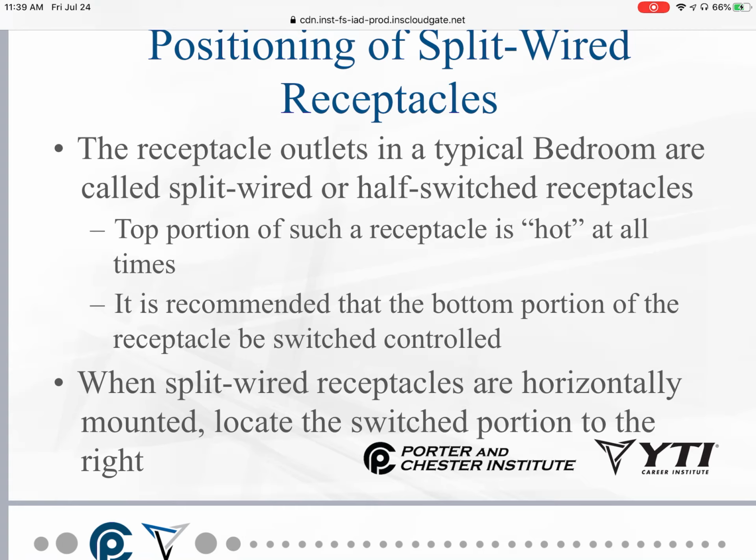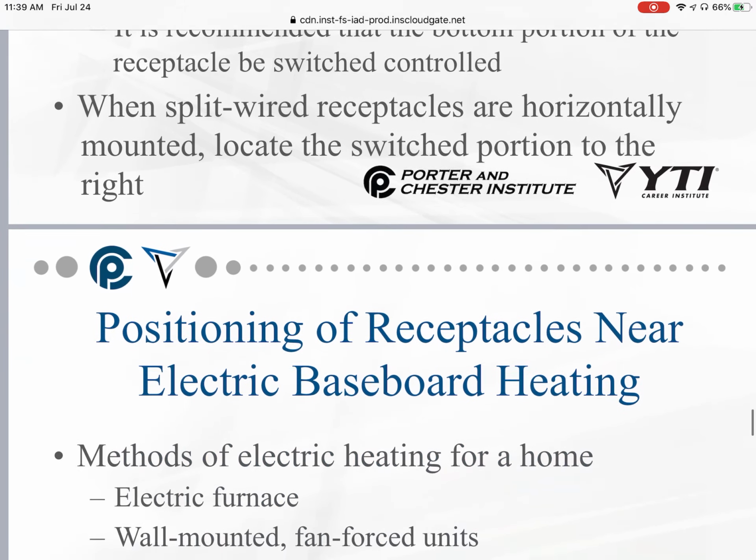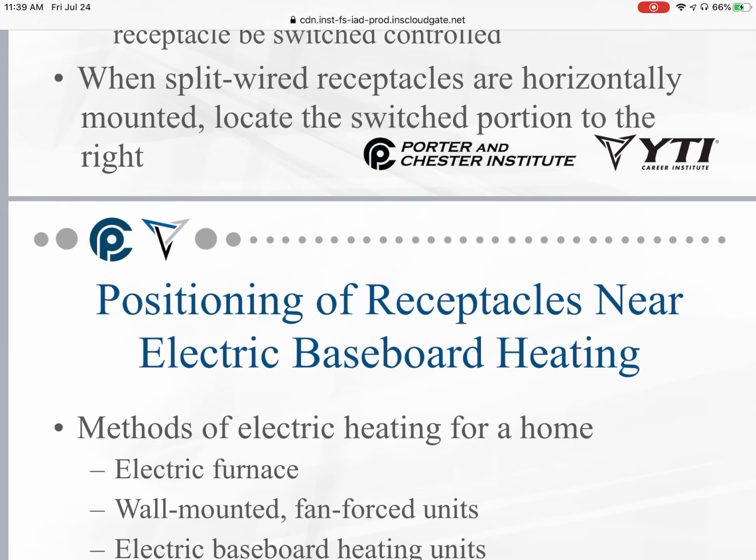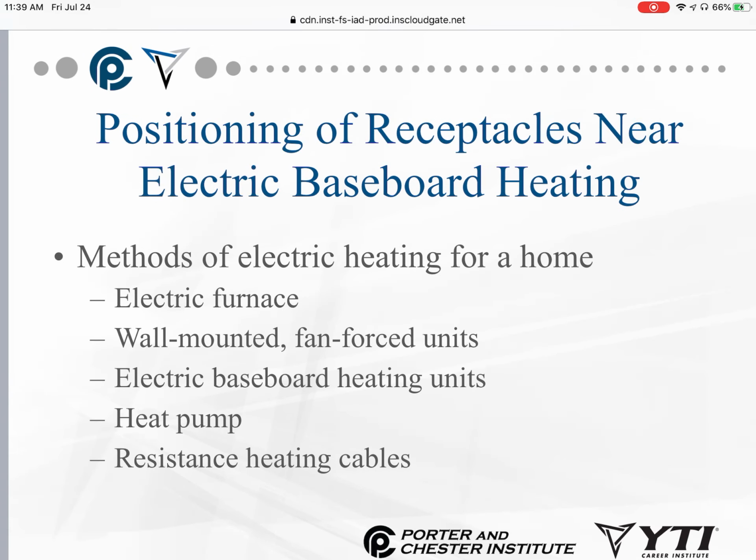Split wire receptacles are horizontally mounted, the switch portion to the right. So if you have horizontal, you should stay to the right, I guess, on that one. I don't know how many horizontal ones you're going to find, but you may occasionally find them that way.